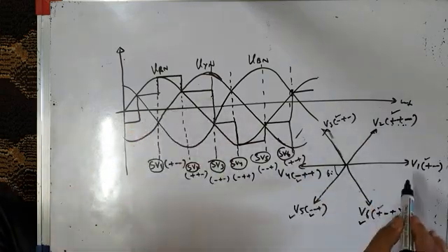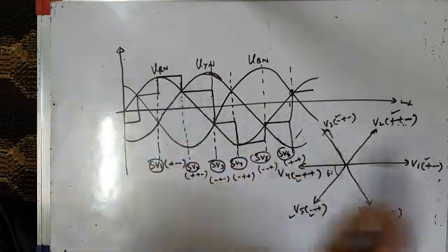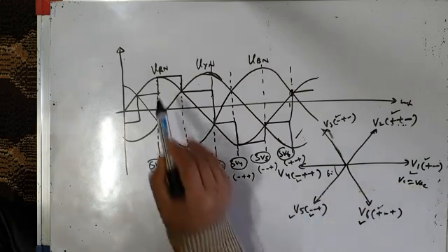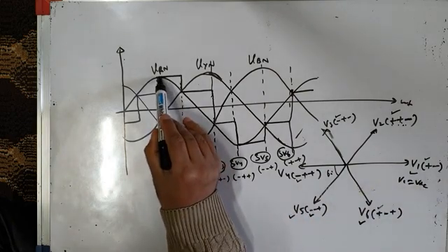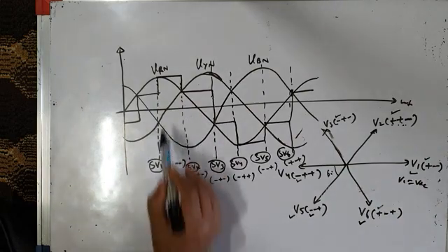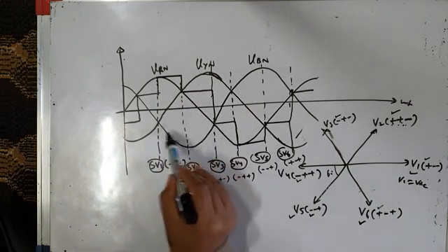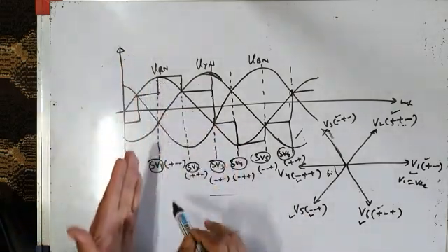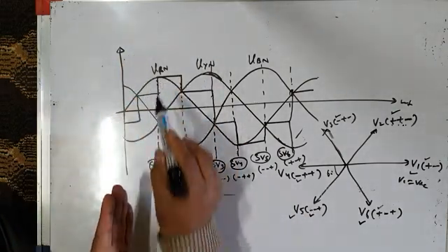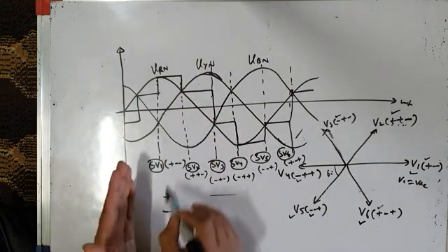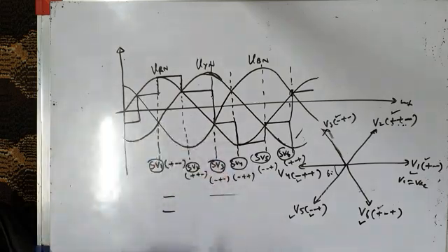इस पे मैंने देखा है कि instantaneous value of phase voltages क्या है. For example, when space vector is here, V1 is equal to VDC, it represents 3-phase voltages, जिसमें VRN का maximum value है, VYN और VBN negative है, I mean some negative. You can draw those VYN and VBN also on the same waveform or separately. So therefore, this represents a set of 3-phase voltages. So VRN is positive and VYN and VBN are some negative values, say minus 1/3 VDC and minus 1/3 VDC.